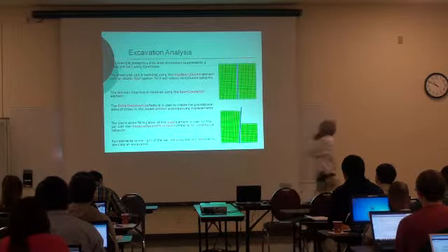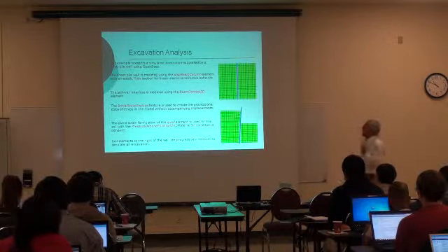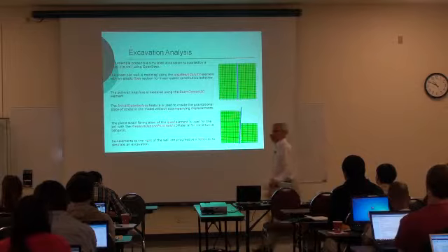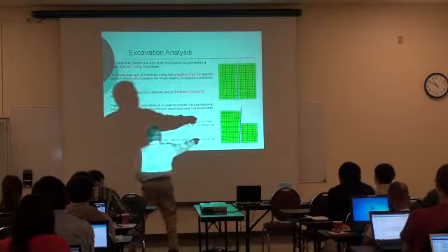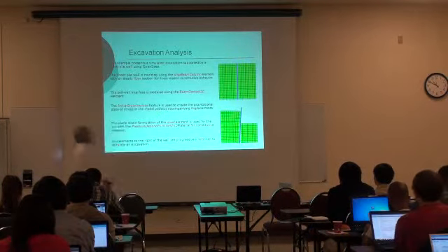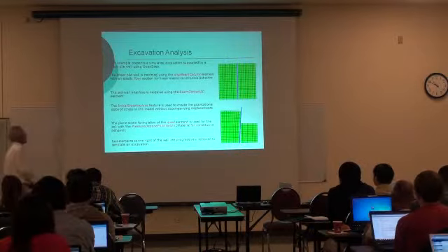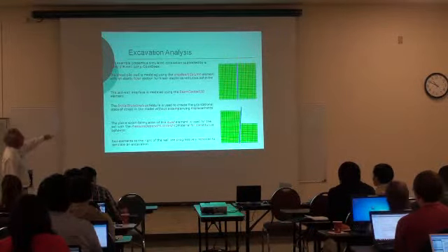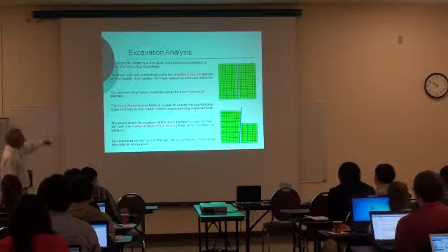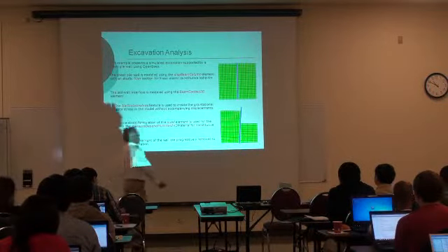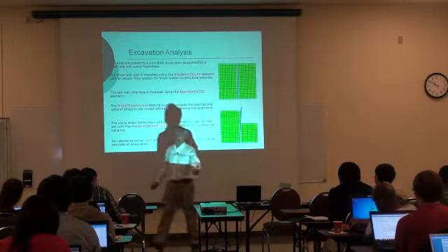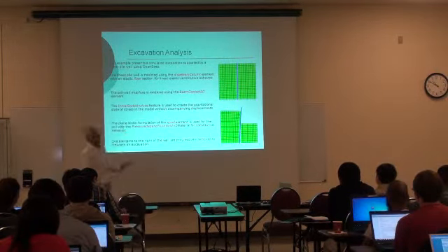This is one where I was experimenting with, it's a different one, it's an excavation. Excavation is another typical geotechnical problem. You have a soil domain, you build your sheet pile wall, or you have a soldier pile wall, and then you excavate. As you excavate, of course, the soil is going to push here, and you will have big demands on your wall. So how to capture that response?